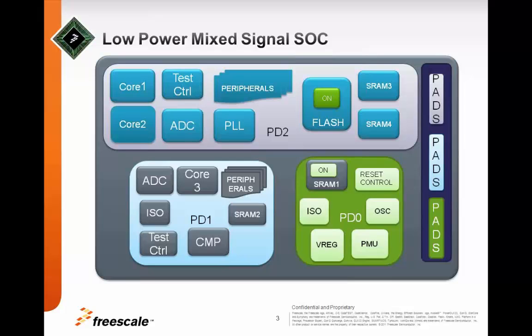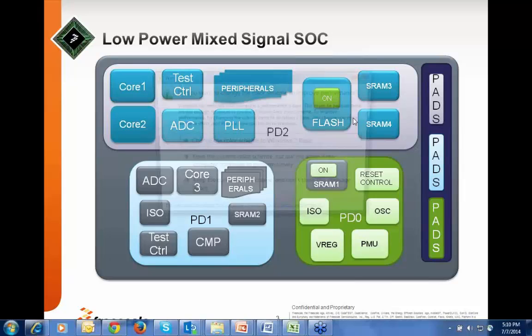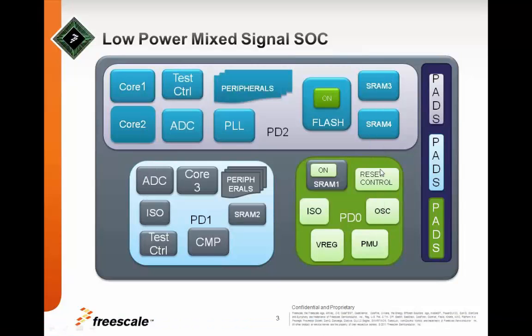And there are multiple pads in the design which can be associated with the switchable power domains as well as the always-on domain in the design. Now, the design supports multiple low power modes, wherein we have the full standby mode in which the high performance PD2 domain as well as the low power PD1 domain can both be switched off and only the PD0 domain is alive.